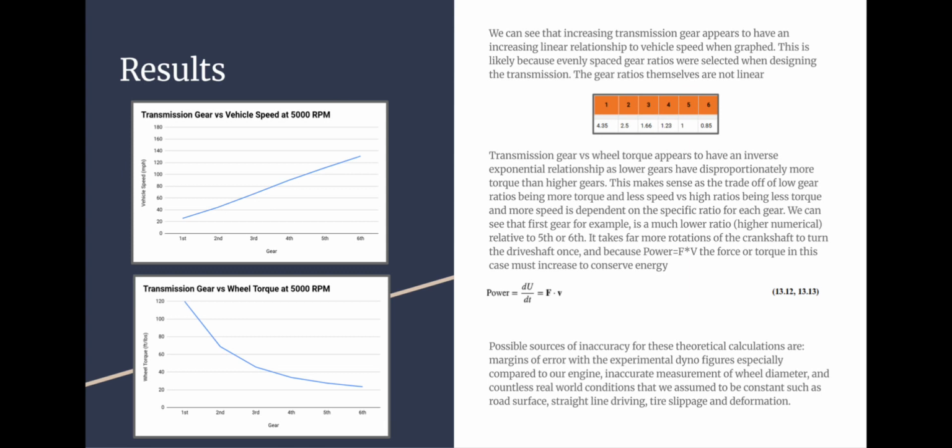And because our power equals force times velocity, the force, or torque in this case, has to increase to conserve energy. Because if you're increasing that velocity and keeping power the same, your force has to increase. So that's why lower gears have more torque.